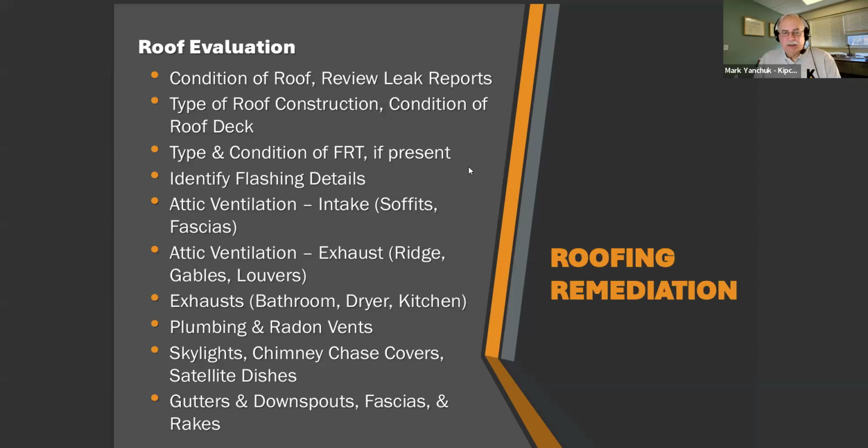These are all issues that need to be addressed during the roofing project. All the vents need to go to the outside. Any combined vents need to be separated, because you can have backflow cross contamination of the air. So they all have to be separated and exhausted outdoors.